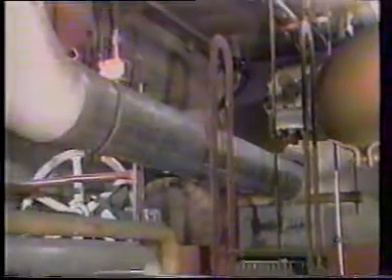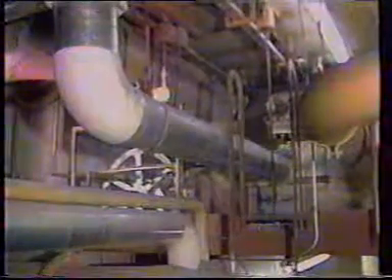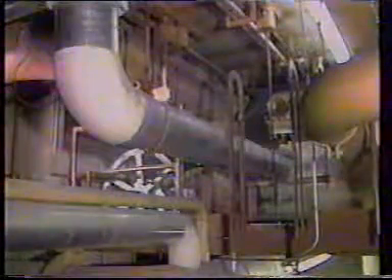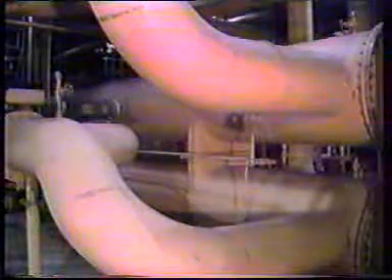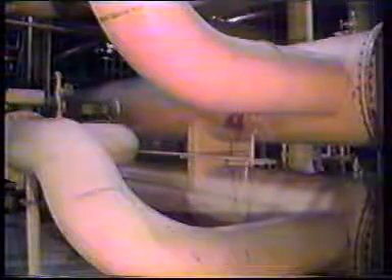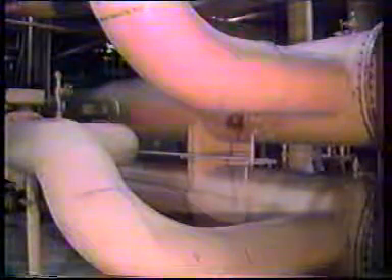When a fluid travels through a pipe, its internal friction and the friction between the surface of the fluid and the walls of the pipe resist the movement of the fluid through the pipe. This friction or resistance to flow depends on the viscosity of the fluid in the pipe. The viscosity can also determine whether the flow is internally turbulent or laminar, that is, whether the molecules of the liquid slide easily across one another or do so with difficulty. If the flow is laminar, there will be less frictional resistance at the center of the flow, where the molecules are sliding against each other, than at the pipe walls, where friction occurs between the liquid and the pipe surface.